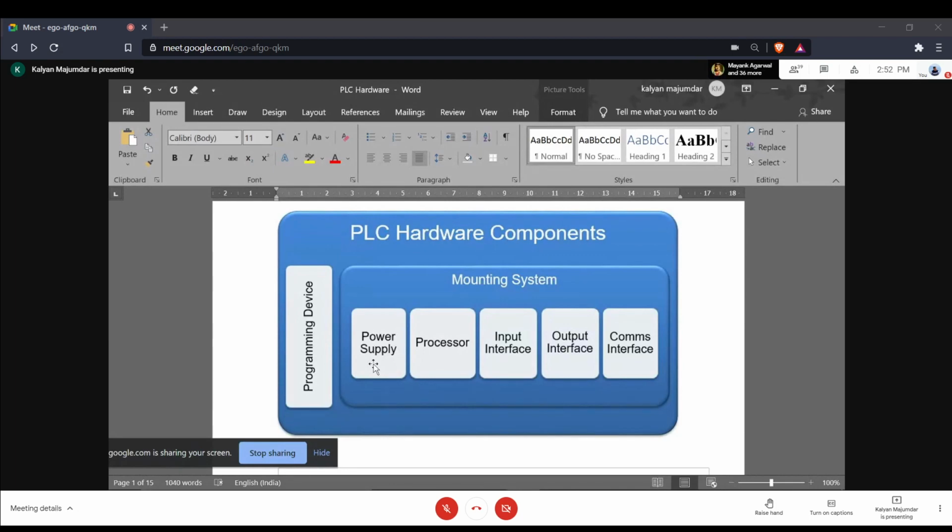It typically looks like a notepad. Typical screen size is 8 inches to 10 inches. But what is important is it is made for industrial use. That means it's extremely ruggedized. A typical classification is IP65. Probably you don't understand what IP65 means: 6 is protection against dust, meaning it is dust proof, and 5 means it is waterproof. Waterproof doesn't mean that you can immerse it under water, no. But if you splash water on that particular device, even by a hose, nothing goes wrong.